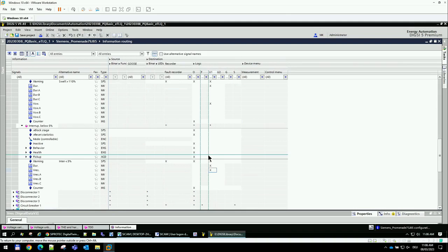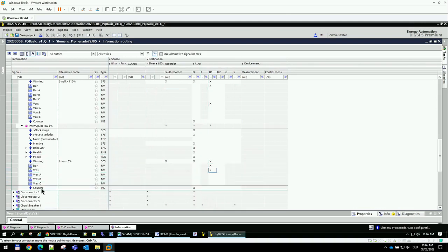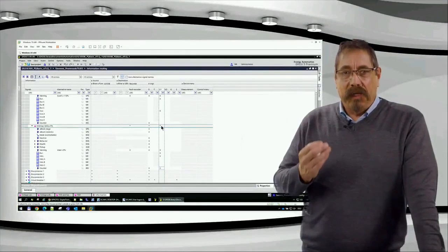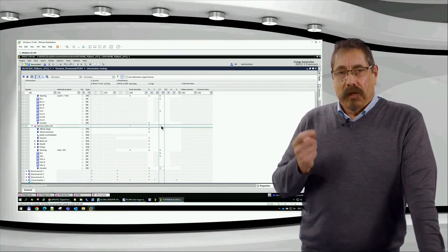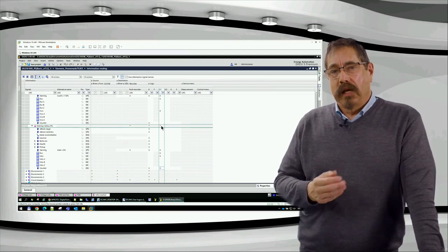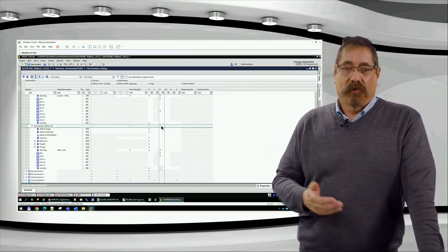And I've forgotten something, the counter, also very important information. I would like to have the counter in my log, because when we do long-term monitoring of a feeder, for example, in a week or a month or a quarter, a year, it's good to know in the log afterwards how many voltage dips have been detected inside this observation time range, for example, 1 year.